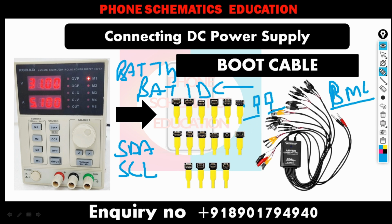So the divider circuit is complete, because in some phones your master IC is programmed so that once the BAT ID or thermal line divider circuit is complete, the CPU senses it and then your phone boots up properly, mostly with BAT ID, battery identification, when your CPU senses whether the battery is there or not.